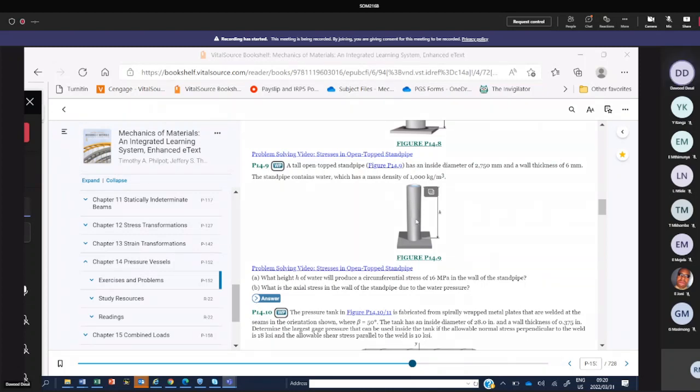Very, very important, because when you do design work for the storage tank, you must use that formula. So pressure is equal to rho g h. Height h is the height in meters. You put it into that simple formula and you get the value for pressure. Thereafter, you can work as you normally work. All right. So you can get some questions, so keep that in mind. Whenever they give you a height, always remember what Desai taught you, eh? Rho g h.